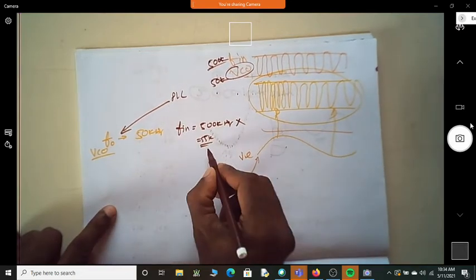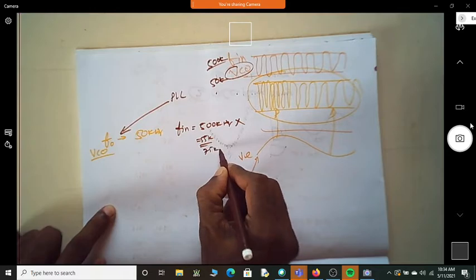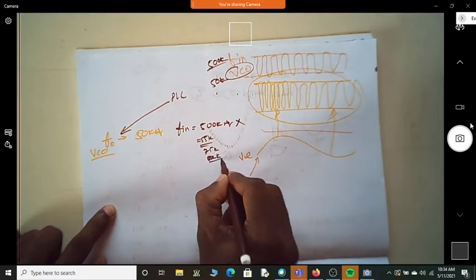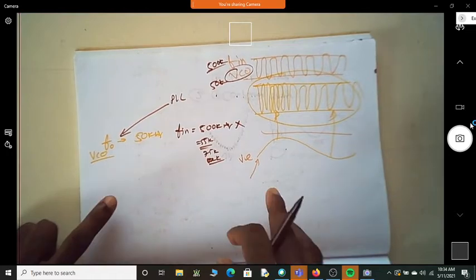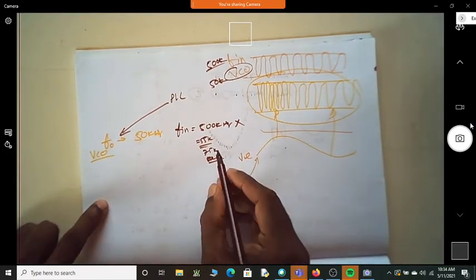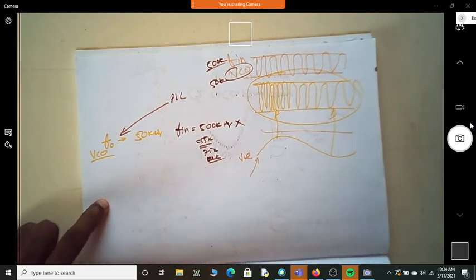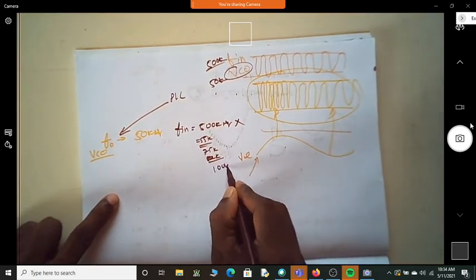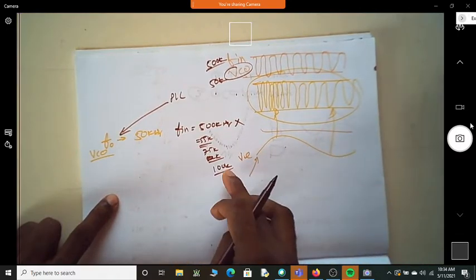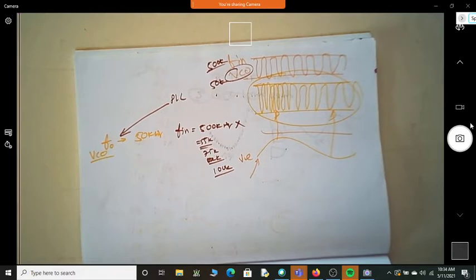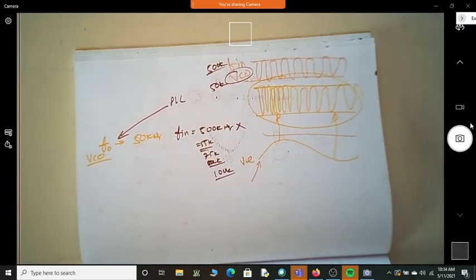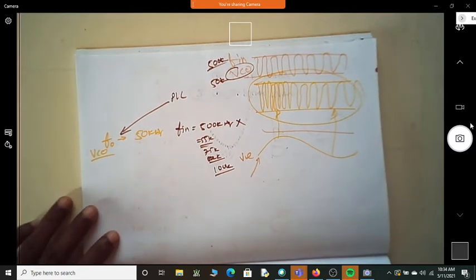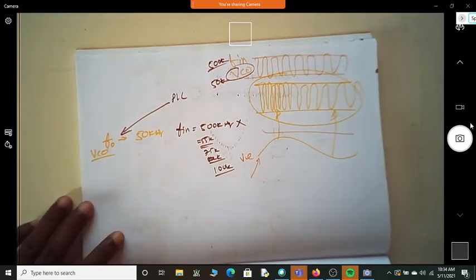Once it gets captured, even if the frequency goes to 75 kilohertz or 80 kilohertz, if your VCO and phase detector have good sensitivity, it can still lock to this frequency. Both are changing. Suppose the change in your incoming frequency is too high and goes beyond 100 kilohertz. It keeps holding, but the increment is so high that it cannot cope with that. Then it unlocks. When it unlocks, the frequency of the VCO goes back to its free-running frequency of 50 kilohertz.